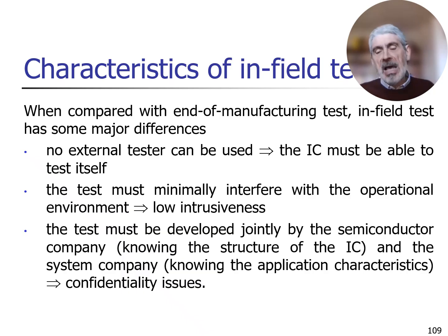Second point, in-field test is done either at power on, in this case the application is not running yet, and I have some freedom. But very often it is done during the operational phase while the application is running. For example, exploiting the idle times of the application. So the application stops for a short period, and during this short period, I will launch the test, then the application will resume. So I need to interfere in a minimal manner with the application. I cannot disrupt the content of the flip-flops or of the memory. And the duration should fit the idle period I can use.